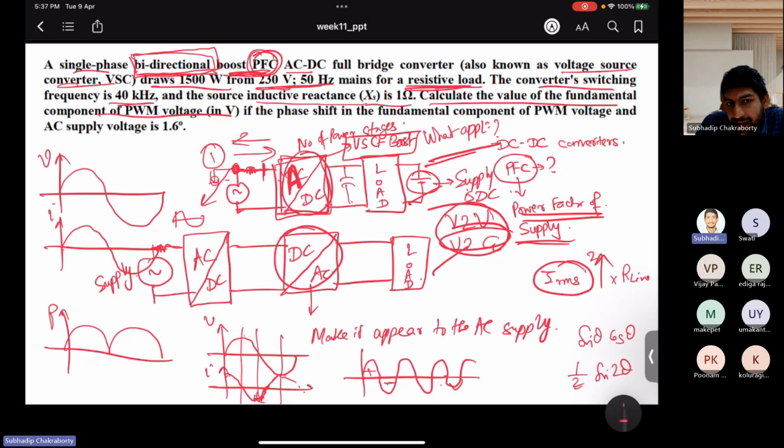Knowing that, where will the pulse voltage appear? On this side or this side? A or B? Can any one of you tell me? The PWM voltage will have switching harmonics within it, and other harmonics also. Depending on the size and selected rating of the inductor, you can eliminate some harmonics. That's why you use interfacing inductors in converters, but can you tell me which side the PWM voltage will appear?